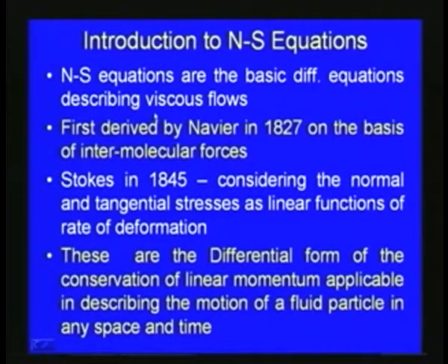the basic differential equations. We have already seen the form of Cauchy's equation, and based upon Cauchy's equation, the Navier-Stokes equations were derived in 1827 by Navier on the basis of intermolecular forces, and in 1845 in the 19th century by Stokes, by considering the normal and tangential stresses as linear functions of the rate of deformation. These are the differential form of the consideration of linear momentum, applicable in describing the motion of a fluid particle in any space and time.